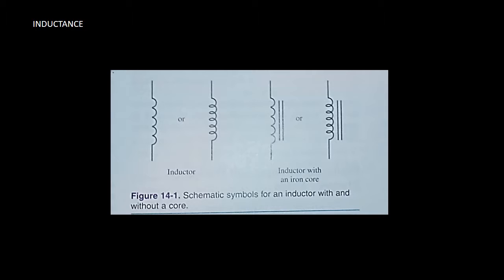As the magnetic field collapses, it again induces a counter EMF. This counter EMF is in the opposite direction of the counter EMF created when the coil was energized. This counter EMF now retards the reduction of current. The inductance of the coil resists any change in current value.